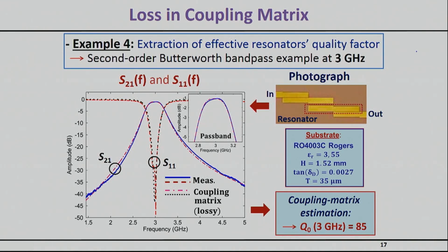So this is an example of a filter shown right here. It's a microstrip filter, and we have not learned yet how to design this type of filter, but you know the concept. The concept is creating resonators. This is one resonator here, this is the other resonator here, this is the input and this is the output. So these are gap coupled resonators, very similar to what we have seen, but the difference is that it's not an edge coupling, it's more of a parallel coupling. So you overlap enough area here to create the correct coupling between the two. The math we have not seen yet, but the concept is known.